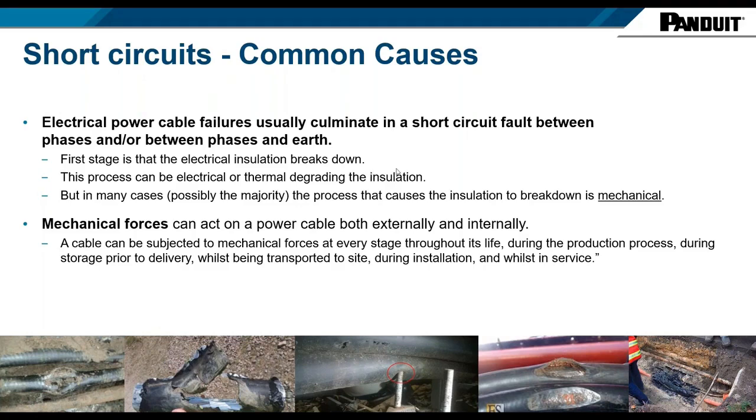So the studding became live, the strut became live, and the person who unfortunately was injured, electrocuted, was some 3 meters away. He touched a live structure 3 meters away from this, but it was all to do with that puncture of the insulation.